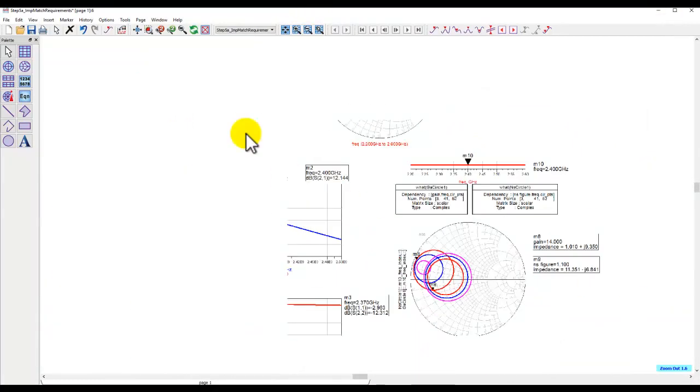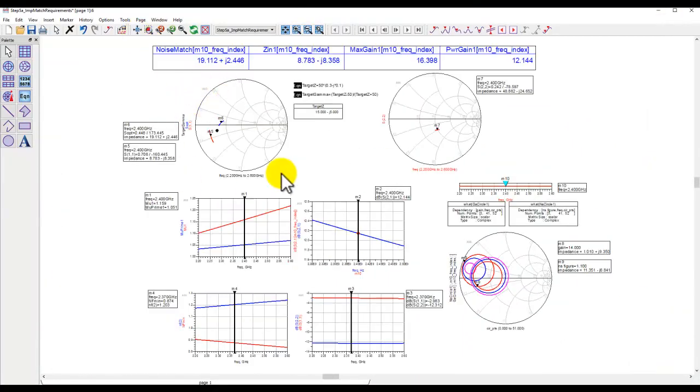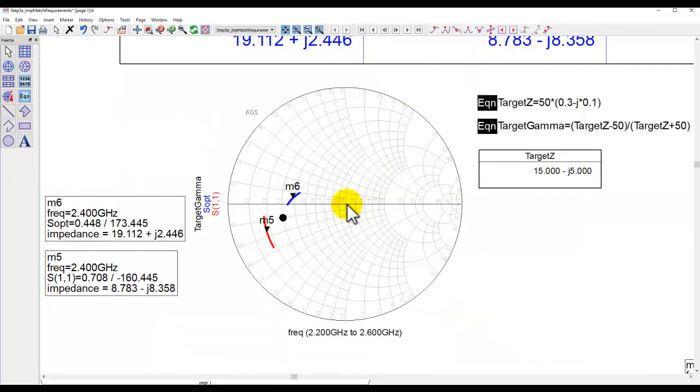Now if we look at the S11 and S22 plot here, S22 is pretty straightforward because you just need to plot S22, place your marker at your desired location, unnormalize the readout of this marker, and you can notice the impedance directly there. So there's no big deal here. The fun or the main consideration in LNA design is how you are going to handle the input matching response. So here, let's focus on that.